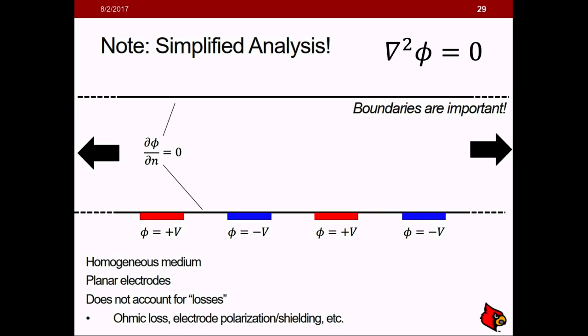Because of that, it's extremely non-uniform, so you're going to need a fine mesh within your numerical simulation to solve for the dielectrophoretic force. Because you're taking a gradient, squaring it, and then taking the gradient of that, any errors from a coarse mesh are going to be amplified through your simulation.